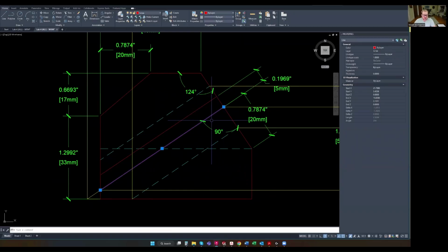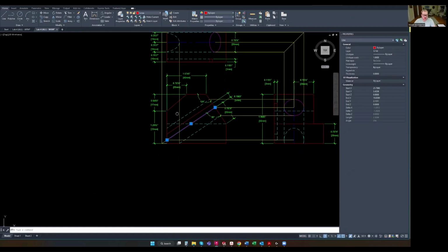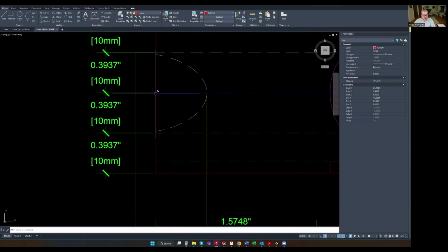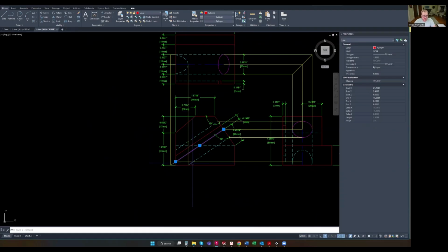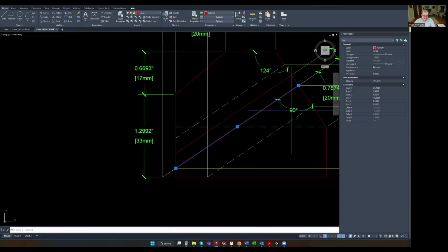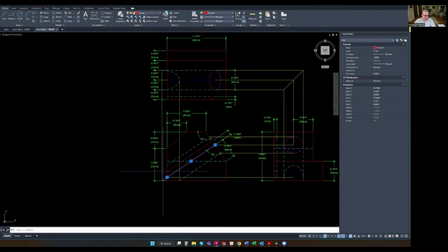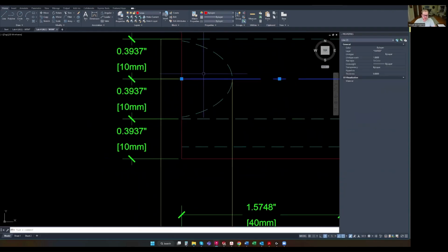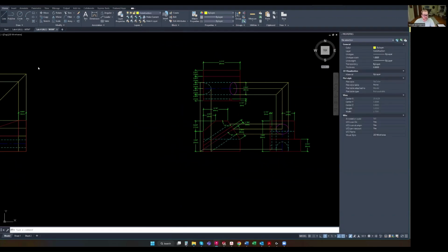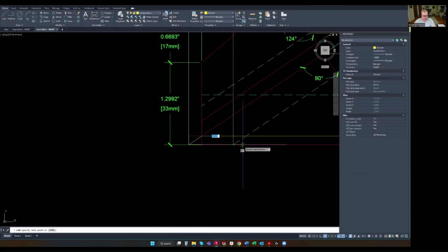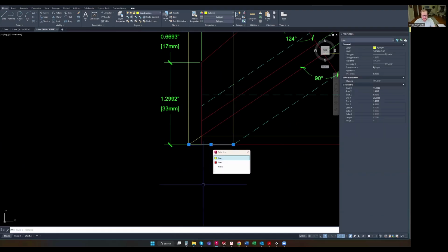When we draw the top view, we can't start our ellipse right at this point right here. When we project this, we have to extend as if this circle came all the way through the part and then was flat on the table right here. And then project that all the way up and start that ellipse where it intersects with the center line in this view. So this ellipse is actually going to be, if this was projected all the way flat onto this table, let's say this is a table that this piece is sitting on. We're going to mirror that.